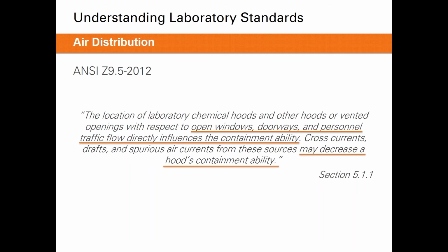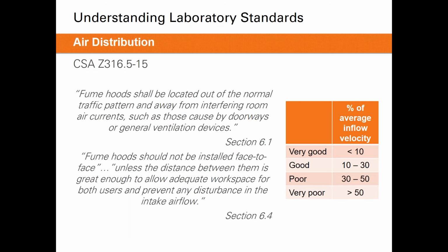Moving on to the CSA Z316.5 standard. It as well states something very similar in that we want fume hoods to be located out of the normal traffic pattern and away from any interfering room air currents. Again, these can be caused by doorways or general ventilation. The second thing that it does stipulate here in the CSA standard is that we want fume hoods to not